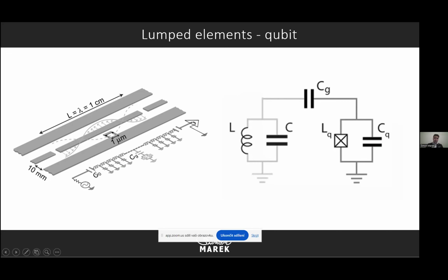The transmission line can be expressed as an inductor and capacitor, and it forms a transmission line, and it oftentimes has 50 ohms impedance, which is used for perfect transmission lines because of great performance. So there won't be any reflections at very high frequencies like 6 gigahertz. So this is used for chip design.